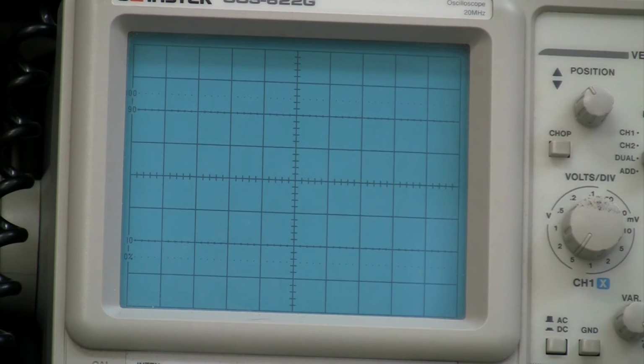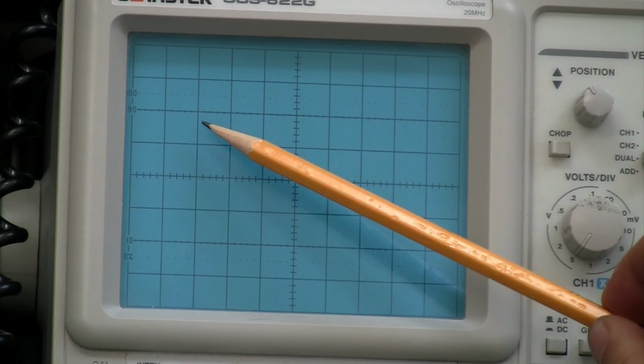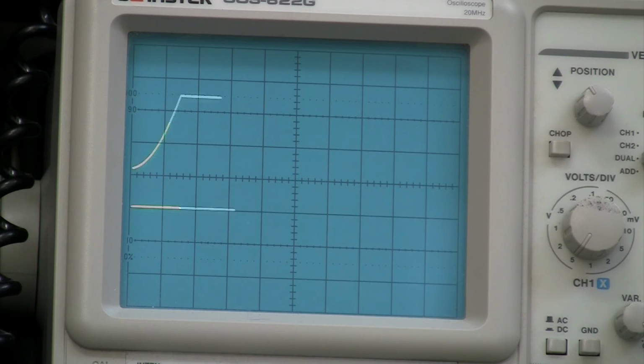So I now have an ADSR envelope that has an additional segment, which I'll just call a hold segment. It's not equivalent to hold in that if you let go of the key, this whole thing's going to change, but it's holding in the sense that while that key's down, it's going to rise up to this 5 volt level and stay there for a while and then decay.